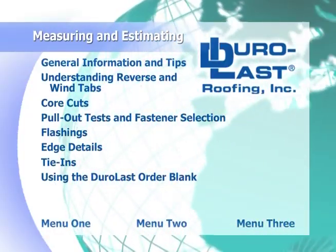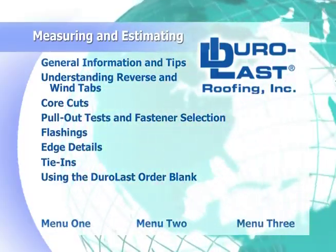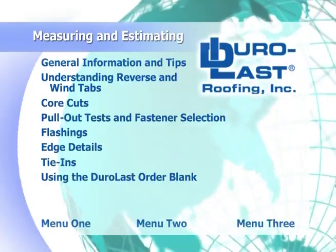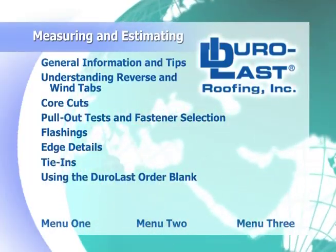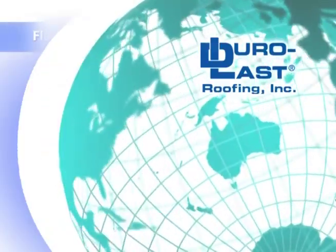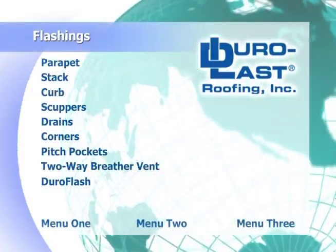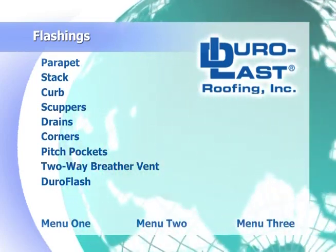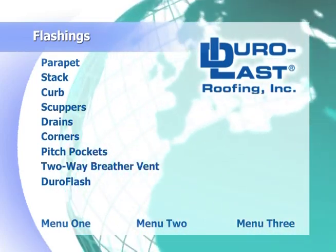Pull the tab tight using handheld grips or a knee puller and attach the fastening tab into the roof deck through the deck membrane at the base of the wall 18 inches on center. Weld the skirt to the deck membrane. The top of the parapet flashing can then be terminated to the wall a minimum of 8 inches high or may extend over the wall to the outside for termination.